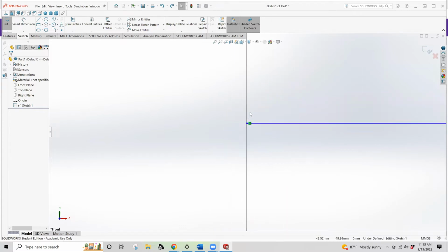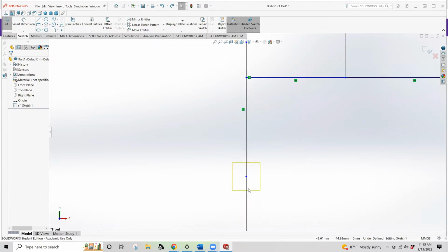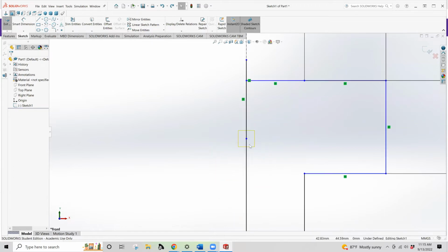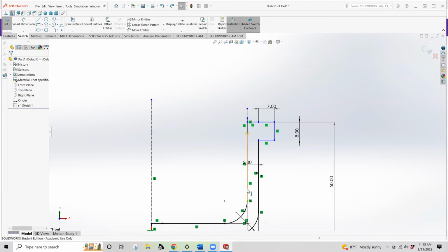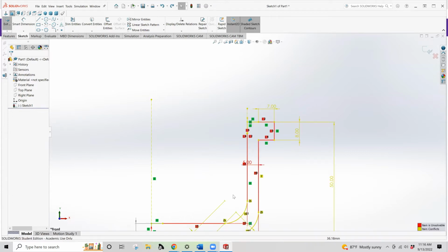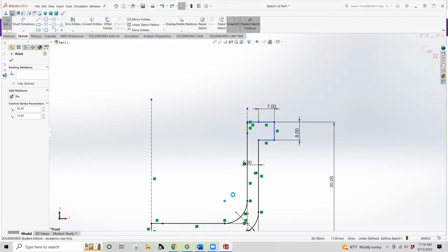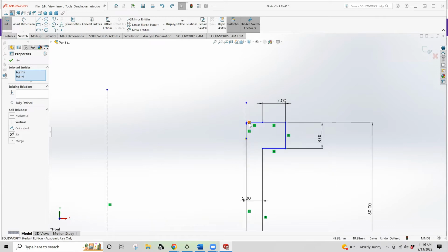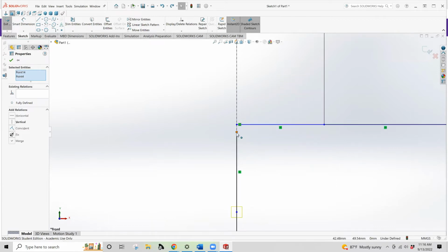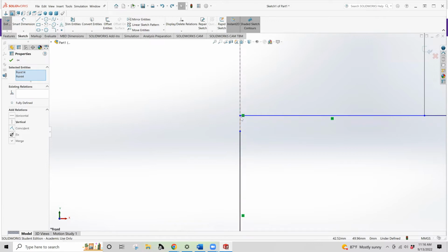Now this doesn't actually become an enclosed volume exactly. What we're trying to do is turn this into an enclosed volume. The length of this line changed. So if I go back and undo a couple other things here, let's step back into the before time. Here we go. So this line, because it's not coincident here, doesn't have a reference point that's coincident with the end of this line.